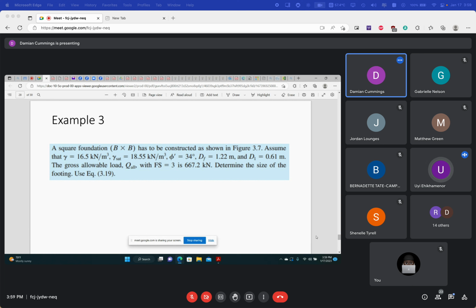Okay. Second thing, sir, the factor of safety. How is it determined again? The factor of safety is, in most cases, determined by the practicing engineer based on his uncertainties and all of that, what factor of safety you want to work with. It's normally going to range between 2.5 and 3. All right. Some, like pile foundations, can go higher, but normally it's between that range.